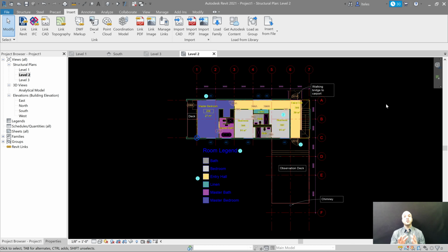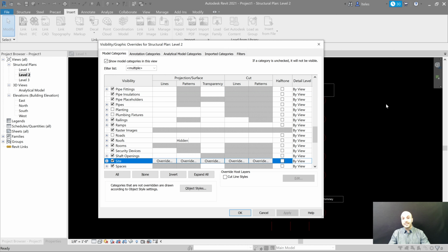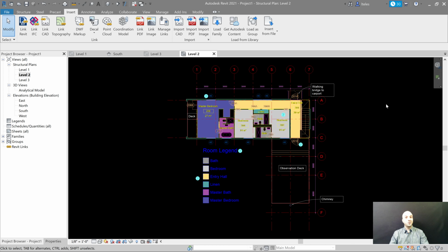So, because we're only working with CAD files, we're not working with external Revit models and having that workflow, we no longer need our project base points visible here. We just use them to locate our CAD backgrounds, our references as we build our structure. So you can turn them off. So VG, SI, spacebar, tab, enter. For those of you that are really getting into keyboard shortcuts, you will start noticing that that is a lot quicker and it becomes more organic to use the keyboard.